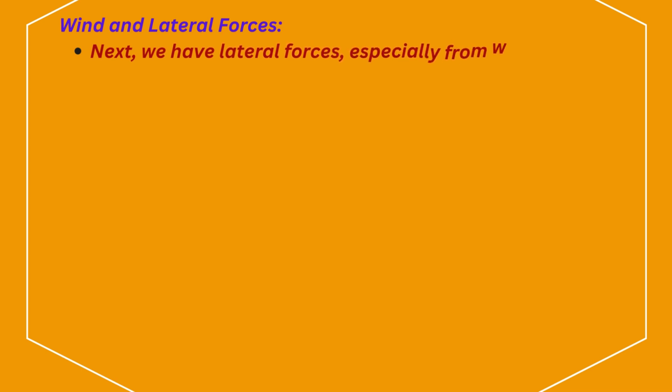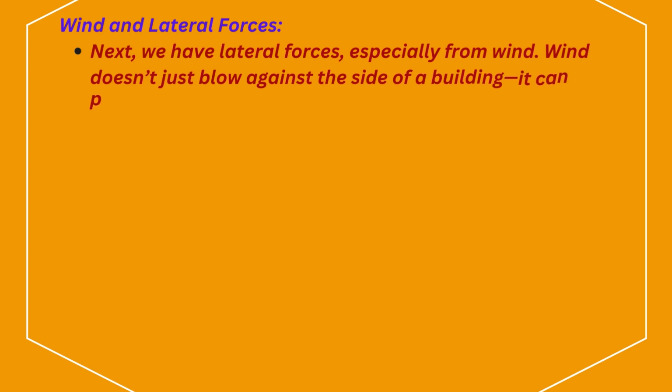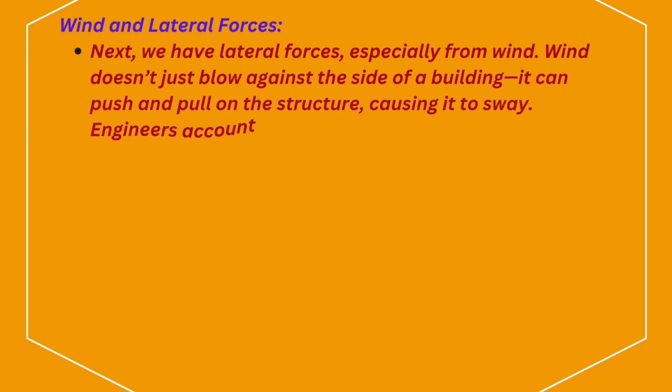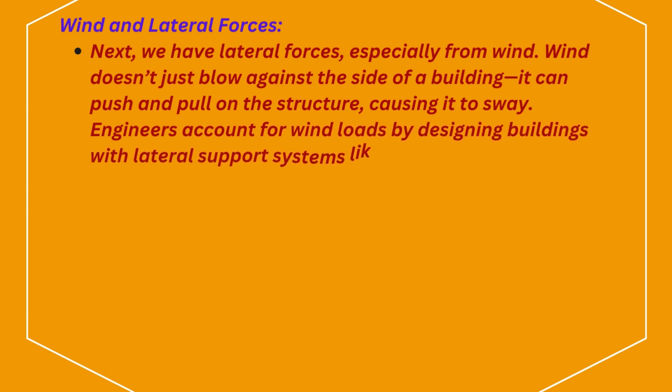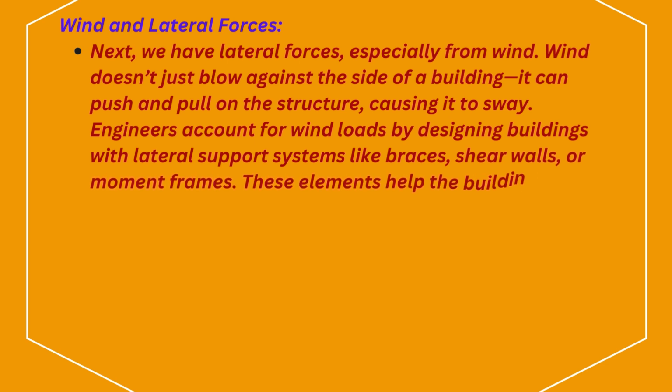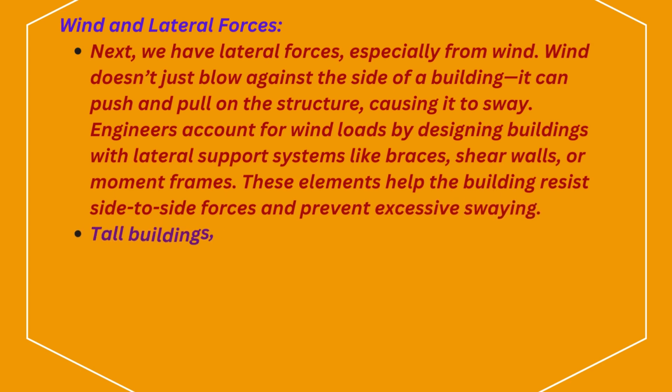Next, we have lateral forces, especially from wind. Wind doesn't just blow against the side of a building, it can push and pull on the structure, causing it to sway. Engineers account for wind loads by designing buildings with lateral support systems like braces, shear walls, or moment frames. These elements help the building resist side-to-side forces and prevent excessive swaying.